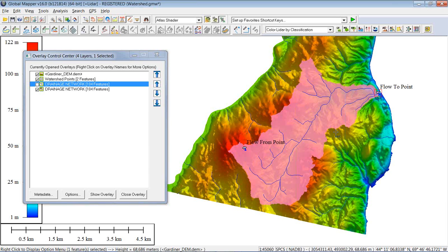So what we're measuring, or what Josie was able to generate through that line with the arrows, was the potential for the terrain to support the flow of water, all other things being equal. Now, we consider that from a water perspective, but think of it as well as a tool that will allow you to analyze outflow from a ruptured pipeline, perhaps. You see there's a break in a pipeline. We were hearing this morning there's one somewhere in the Midwest. That kind of an analysis. Where do we need to put our booms across? It may not be immediately apparent where the terrain flows to. That tool is very powerful for that application.